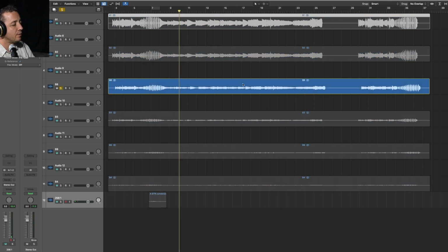So if you turn your gain down a little more, there we go. This is a pretty nice recording level. This is about as loud as you would want it. In the normal volume sections, there's more than enough gain here to get a good signal to noise ratio. And he can go and play loud, and there's still lots of headroom. Even in these loud parts, he could play louder, and you're still not going to go into clipping.